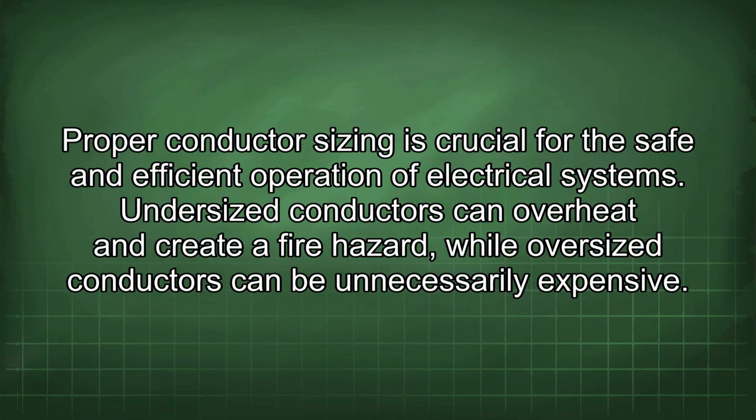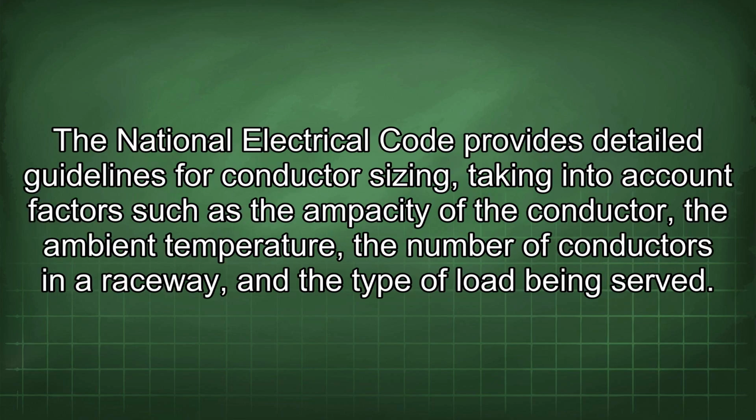Proper conductor sizing is crucial for the safe and efficient operation of electrical systems. Undersized conductors can overheat and create a fire hazard, while oversized conductors can be unnecessarily expensive. The National Electrical Code provides detailed guidelines for conductor sizing, taking into account factors such as the ampacity of the conductor, the ambient temperature, the number of conductors in a raceway, and the type of load being served.